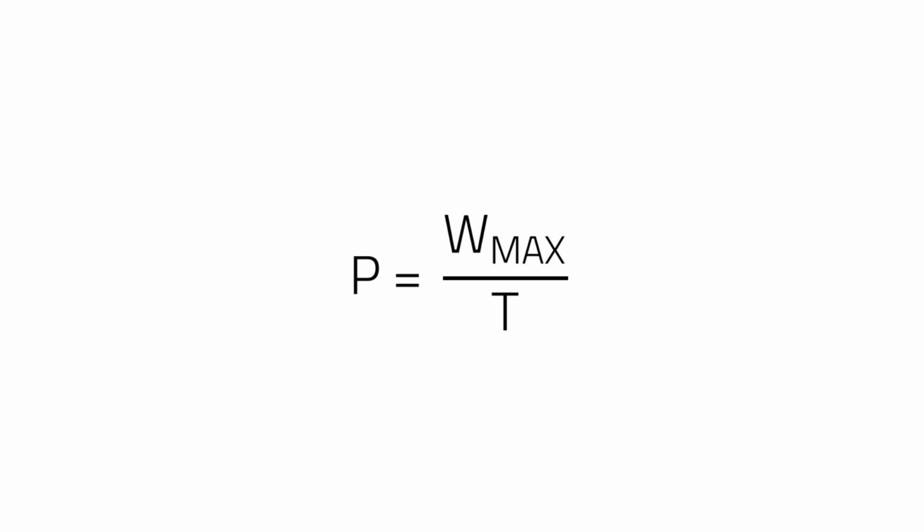So knowing these values, the power is calculated to be 183 milliwatts. The varistor would therefore also be suitable for a surge interval of 20 seconds, whereby the power would then correspond to 549 milliwatts and would be below the max power loss of the selected varistor, our 600 milliwatts.